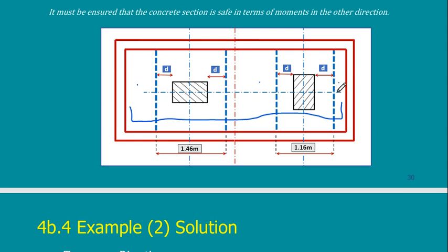In case I find that the distance between this bar and the one next to it is very close, less than 20 centimeters, maybe in the range of 10 centimeters, I can just use one bar like this and remove this portion and use the one next to it to be like this, the opposite.